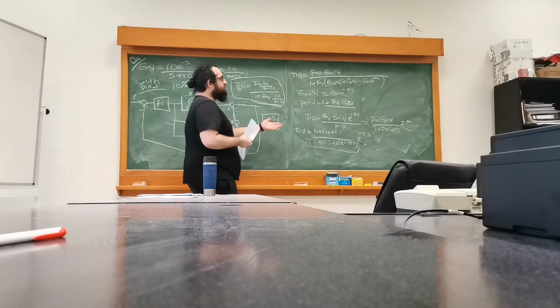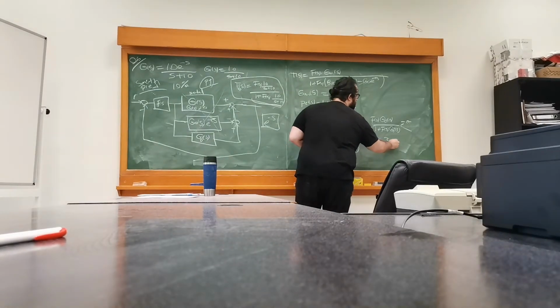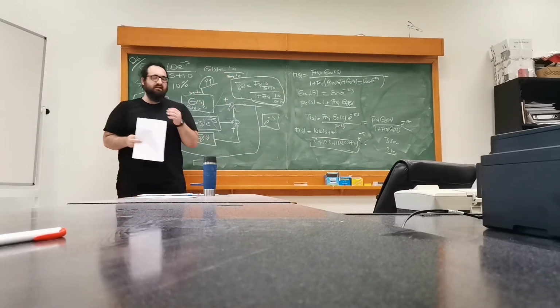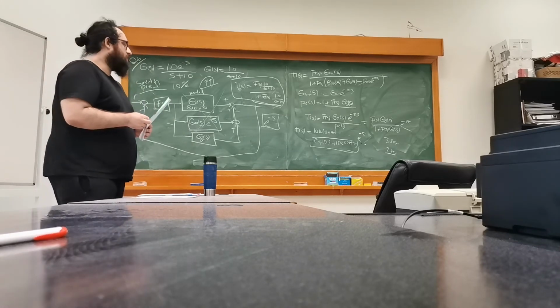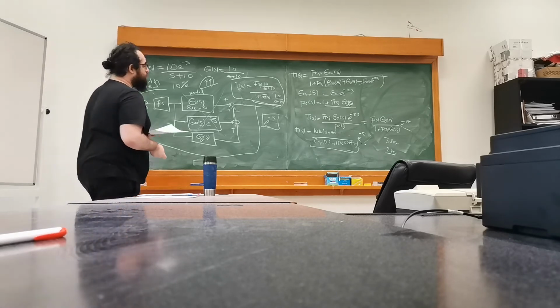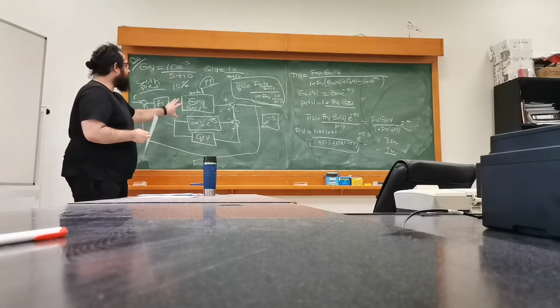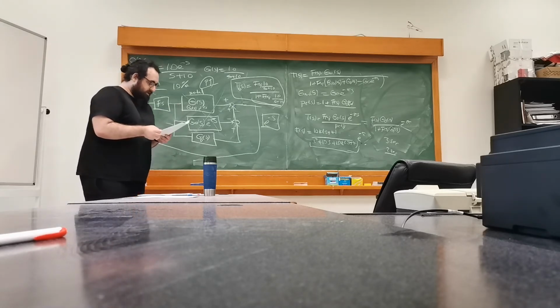So if I'm choosing a settling time of, for example, 3 seconds, I should maybe use 2 seconds of settling time for this system. Since I already have 1 second of delay, I might match this 3 seconds mark. Then you go ahead and design your controller as you wish for the minimum phase part of the system. And if this is working, then you will get the job done.